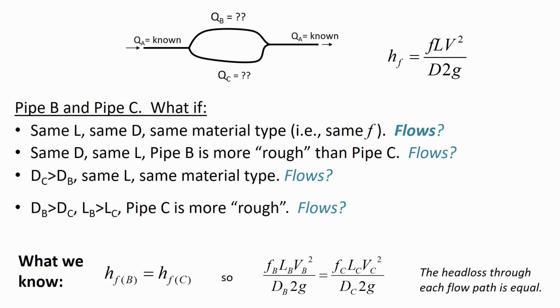So these first two are kind of canceling each other out, because the pipe that has a longer length is going to have more resistance compared to the pipe that has a shorter length. And the way to know that is to look at what's in the numerator and what's in the denominator of the Darcy-Weisbach equation. Anything that's in the numerator is going to give you more head losses when the number is larger. Does that answer your question? Okay.